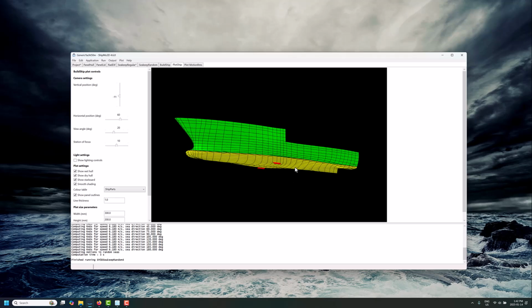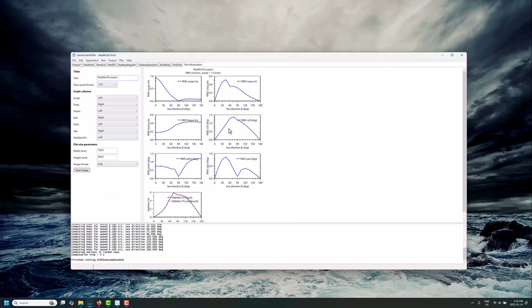It's incorporating the wave height and the resulting motion of the ship and normalizing the roll damping from an equivalent power dissipation. The implication is that you do get a damping effect from the fin stabilizers that changes with wave height. It's a really robust way to capture the hydrodynamics of these kinds of nonlinear appendages. And as it's a full 3D formulation, you're getting the effects of what the fin stabilizers are doing no matter where they're placed on the ship, and also the relative sea direction.